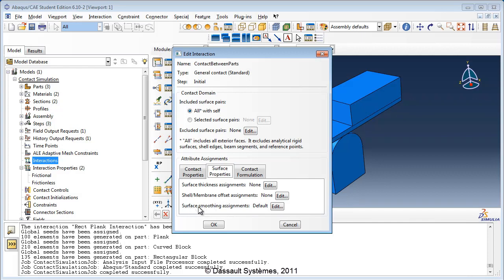Surface smoothing was discussed in the Contact Pairs tutorial. Curved geometric surfaces tend to be approximated as a faceted group of connected element faces rather than their true geometry, which can cause inaccuracy in contact interactions. Surface smoothing overcomes these difficulties by more closely approximating the smooth surface behavior with continuous normals during an analysis.